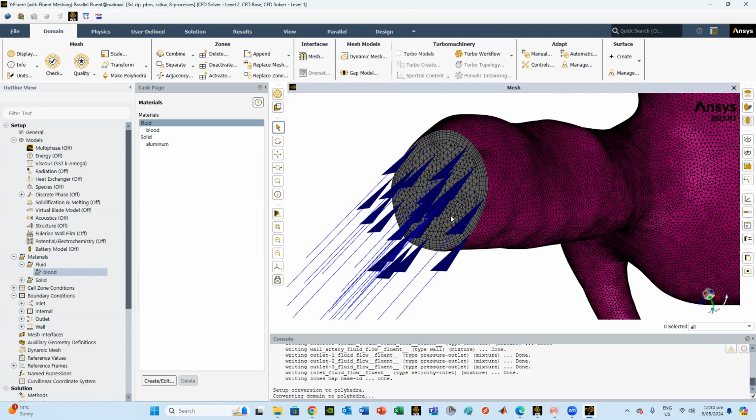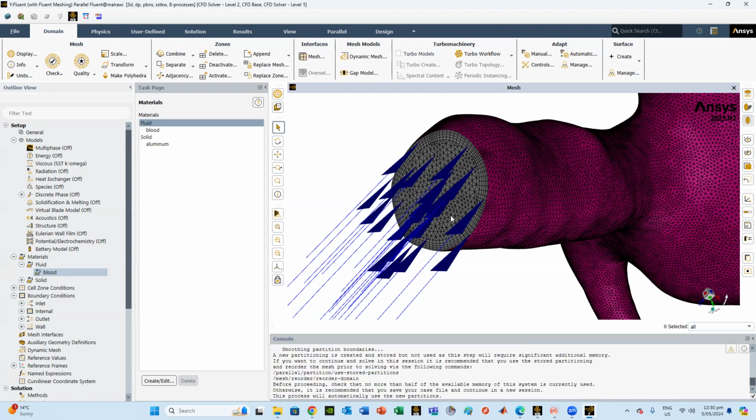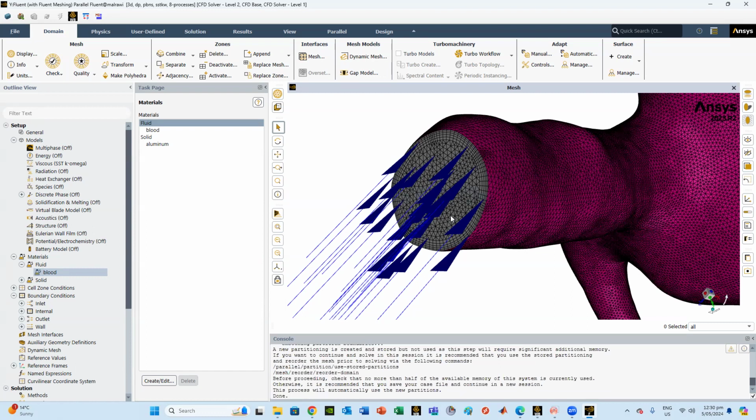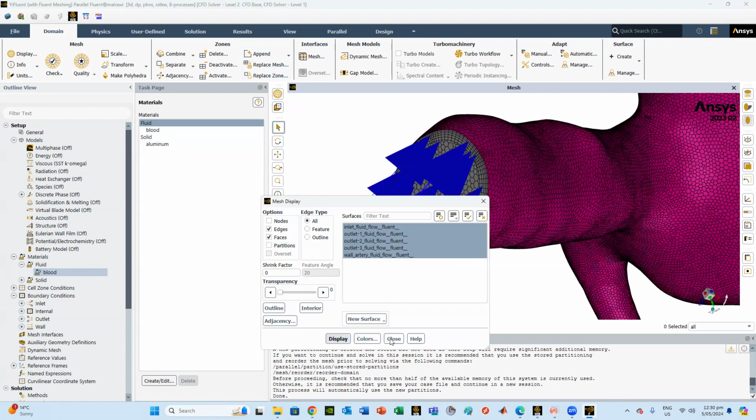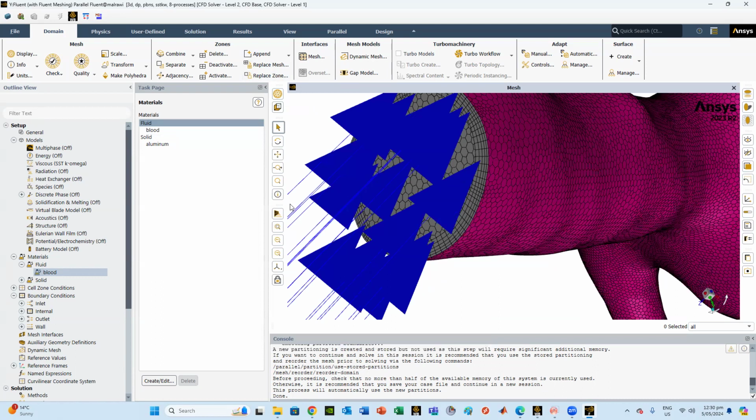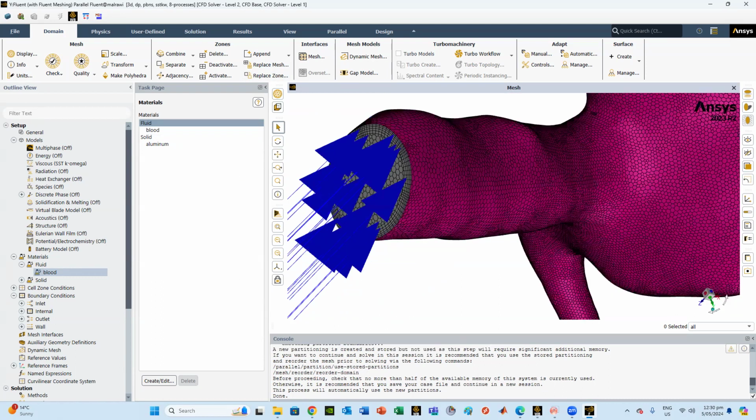Be a nice mesh with polyhedra. The purpose of using polyhedra, the results will be still acceptable, no issues. However, they will reduce the simulation time and make it really faster, especially for this recorded video. So optimizing polyhedra mesh. All right, so it's done. Display, you can see the mesh is changed to polyhedral. Awesome.